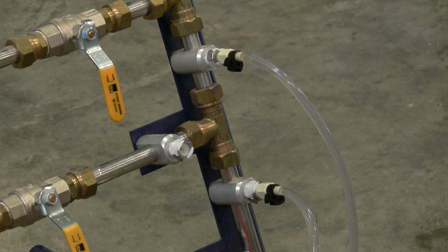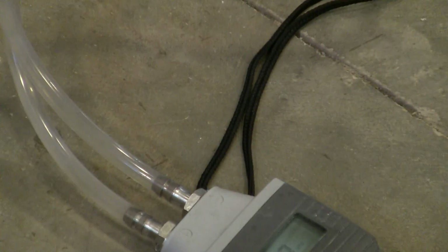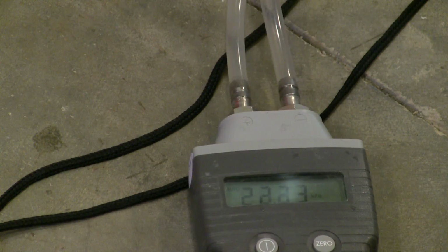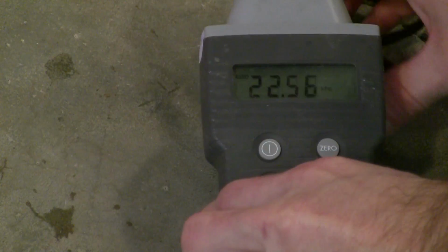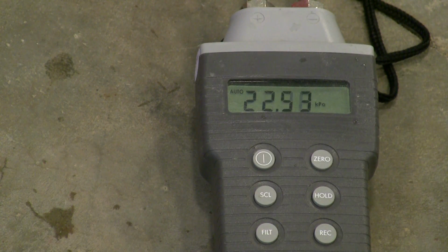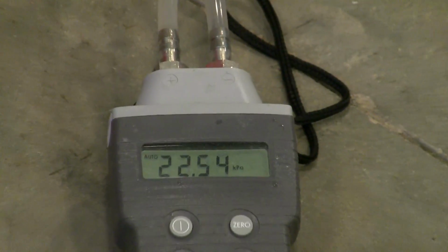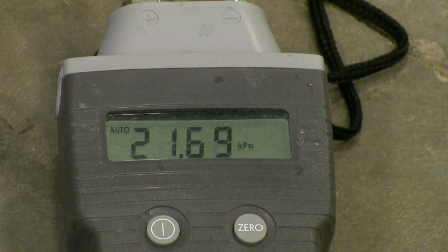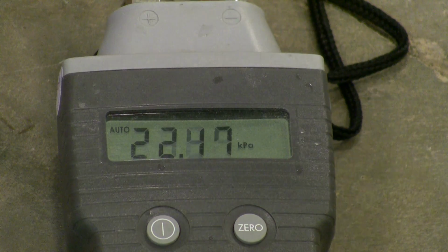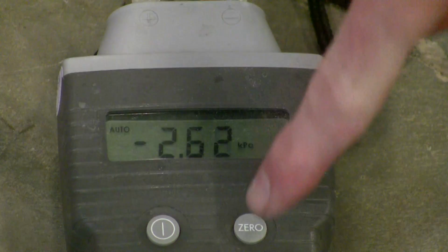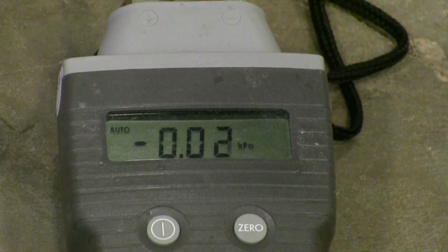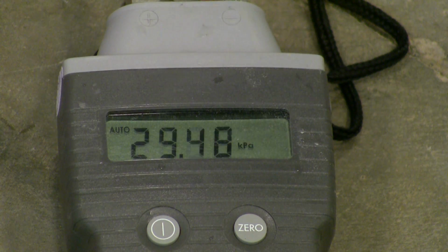Okay, so I'm turning on the pressure meter. Let me tip it up again. Okay, we are getting some pressure measurements. Let me close the valve so that there's no flow, and that should go back down to 0. Okay, so closing the valve. Not quite 0, let me zero it. Okay, it's maintaining 0. I open the valve again to its original state.